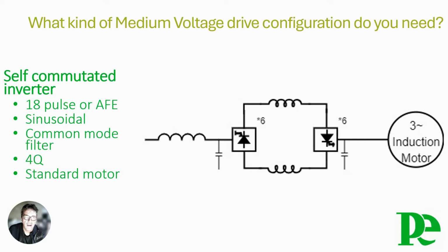While other topologies of medium voltage drive require an isolation transformer, the PWM-CSI version with an active front end can be used without. While this is a compelling sales argument, it is quite important to note that this configuration does not provide for the benefits of the use of an isolation transformer.